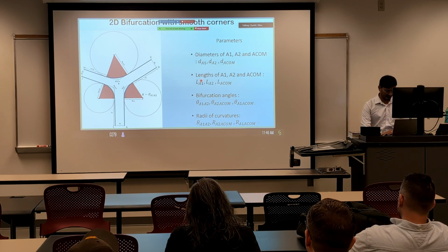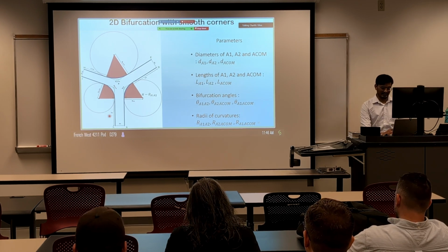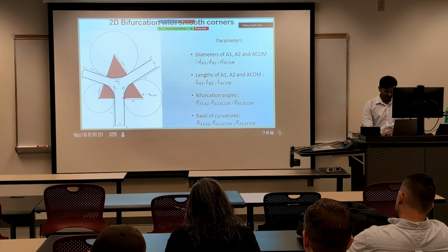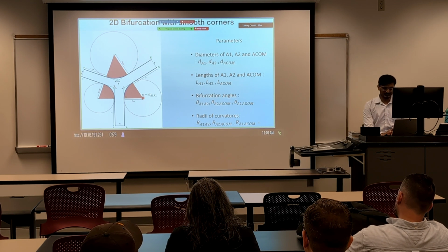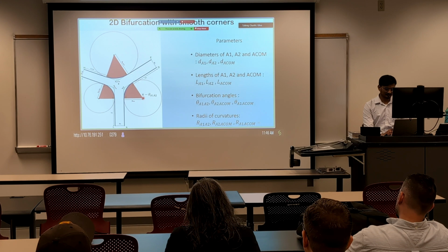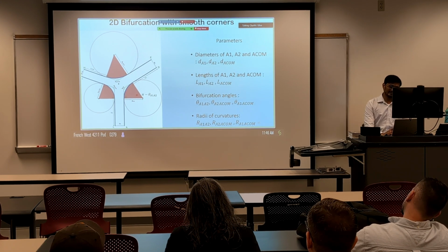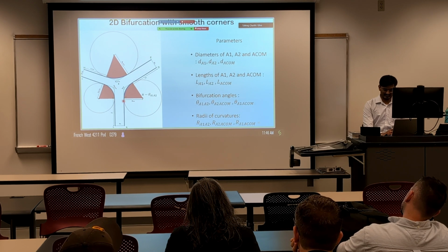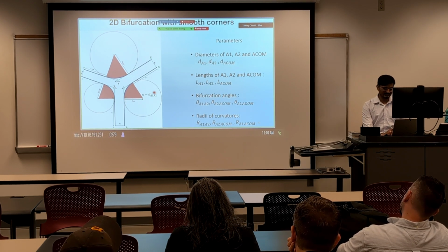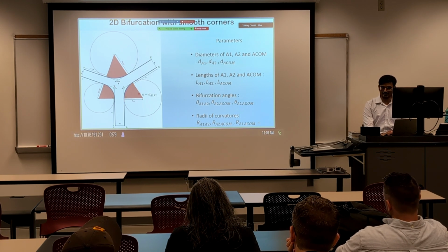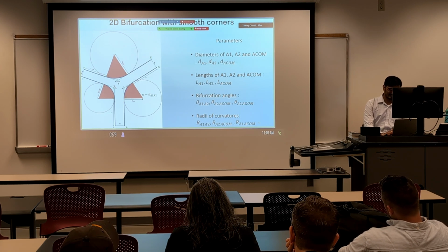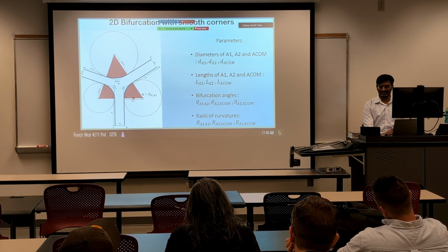what we can do is we can simply start from the given specified point, and we know the L, so go up, and from here construct a perpendicular, because we know the R value as well, and then you can get the center of this right hand side circle, and since this value is given, you can move this radius line with an angle phi minus theta, and then you can move along that direction to get the point C. So basically you have B and C and the angle between them, hence you can construct all these points by discretizing the angle in between.